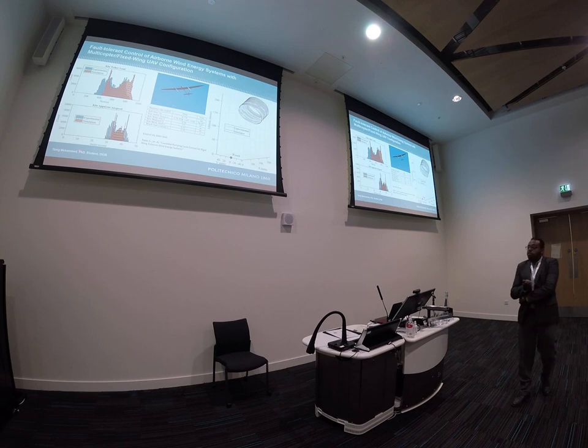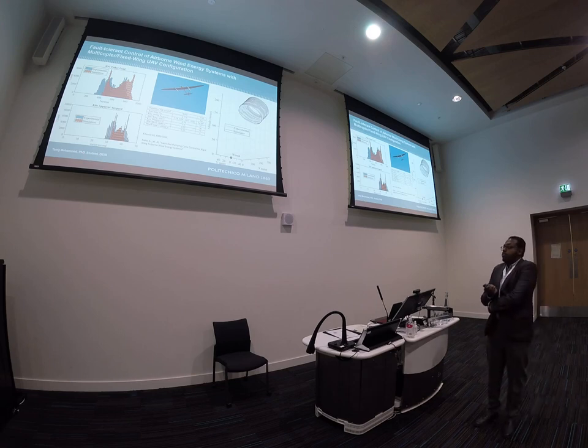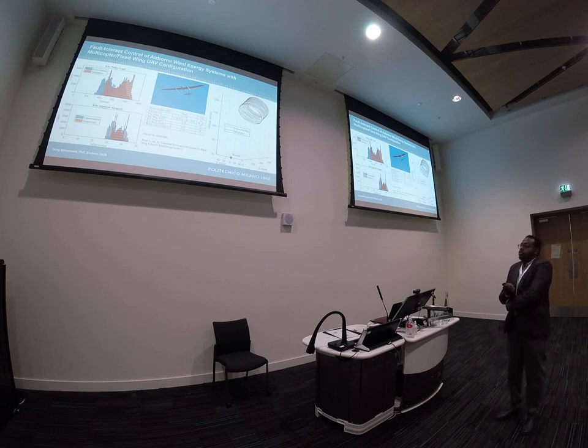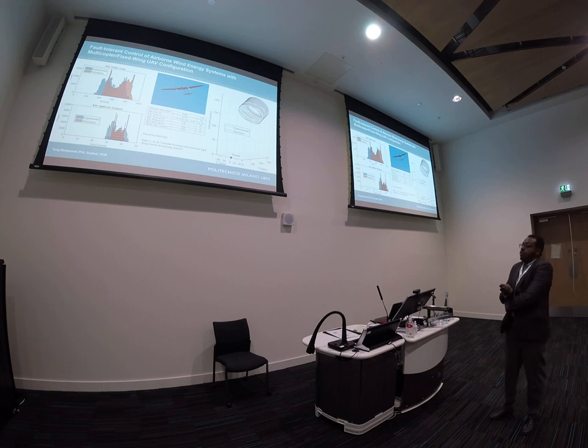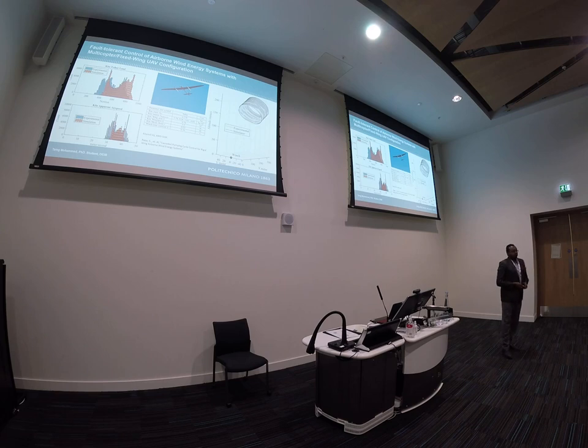The second thing we compare to validate the simulator is the histogram of the kite airspeed. In the experimental data we also have two peaks, one at about 33 meters per second, the other one around 40 meters per second, and the simulator in orange has the same peaks, so a good match. So we consider that now we have a valid simulator to test our control.